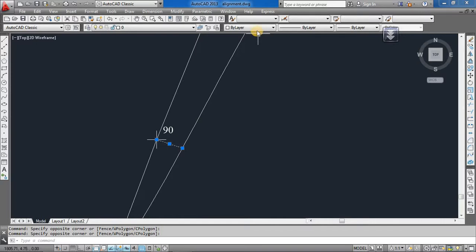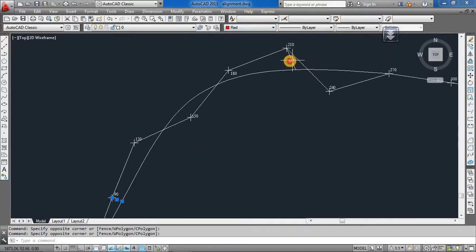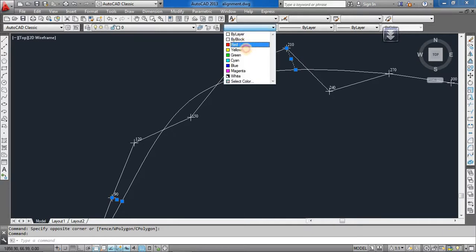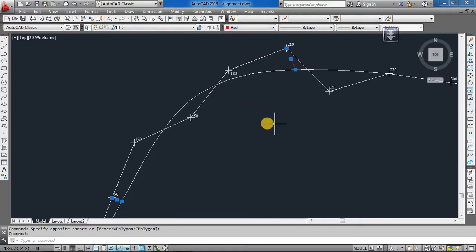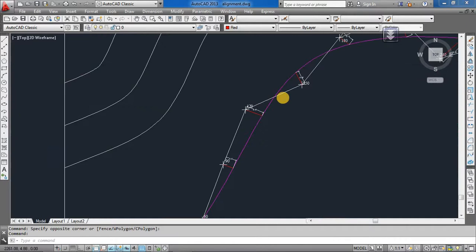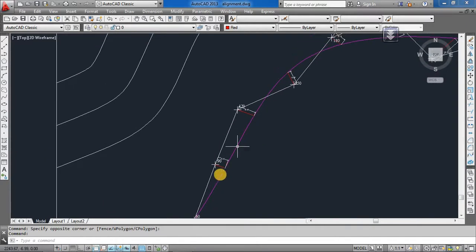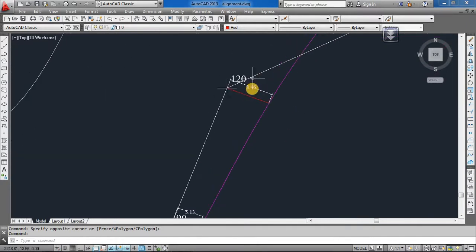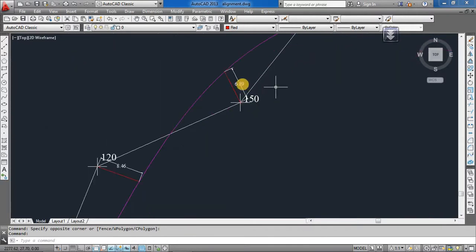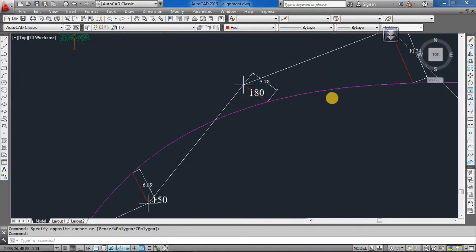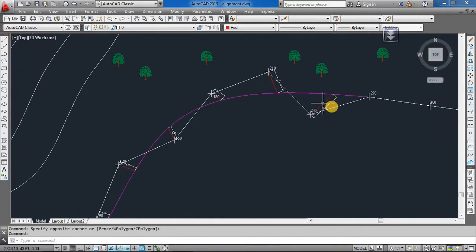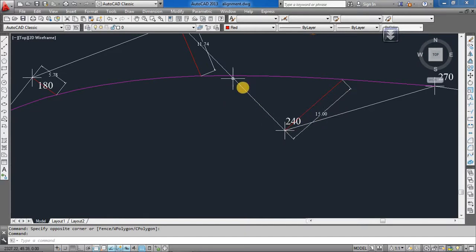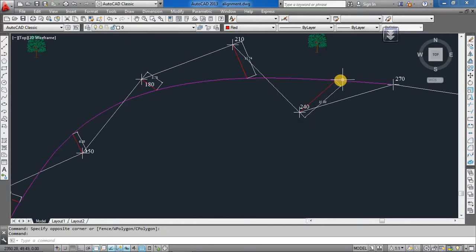that is the deviation of the canal from the center line. Okay, so you should get all the distances of these lines. As you can see, this is the final one. Here at 90 meter the distance is 5.313, and 8.46, 6.89, 5.78 and 11.74. At this point the perpendicular will be drawn here, the line will be drawn like this and rotated by 90 degrees. This one will be the deviation which has happened.